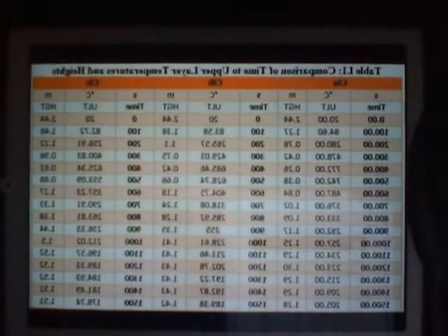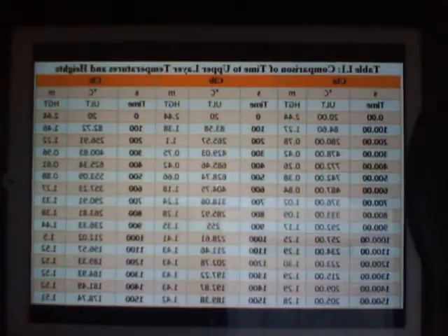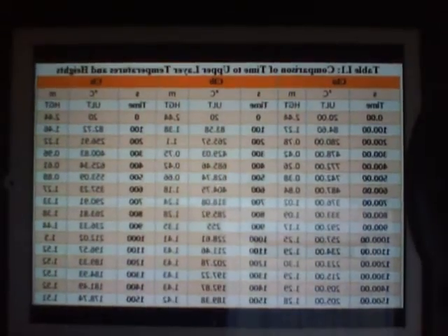And you have a comparison of the time, the upper layer temperatures, and the heights of each, which will demonstrate exactly what I just told you, that basically the less obstructions and the more open to the outside world, the more tenable the structure is going to be for anybody inside trying to make an escape, or it's going to make it easier for firefighters to effectively put out the fire, because they're going to be able to make a better assault on the fire with that ventilation.